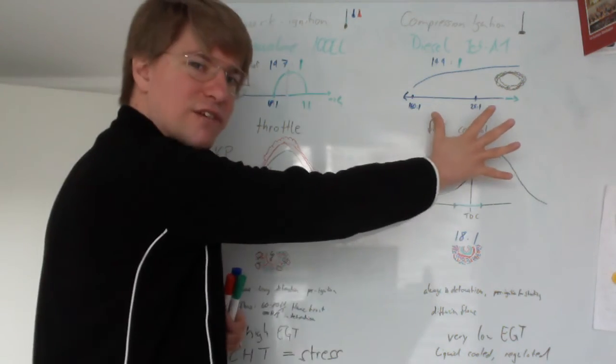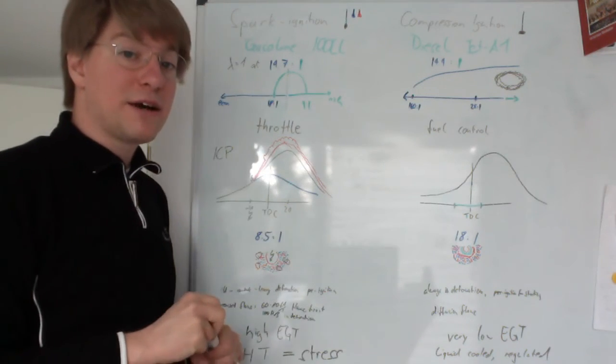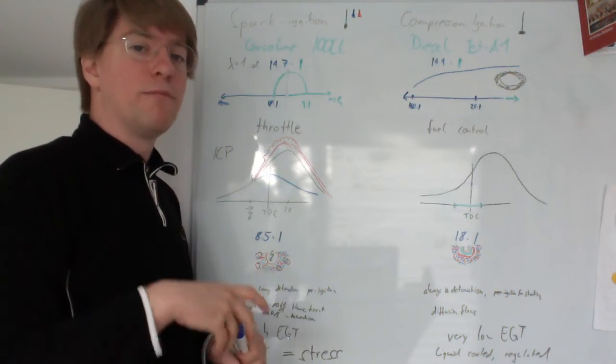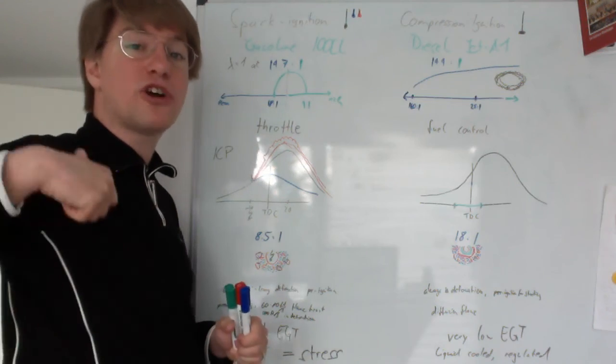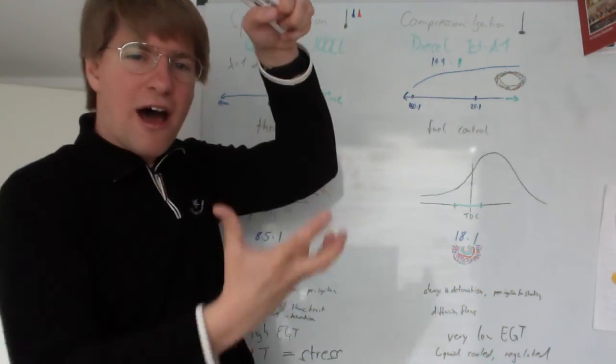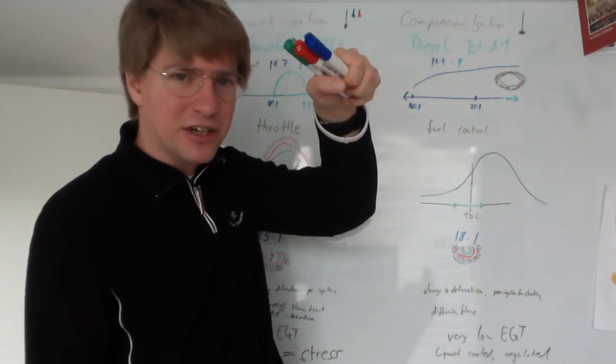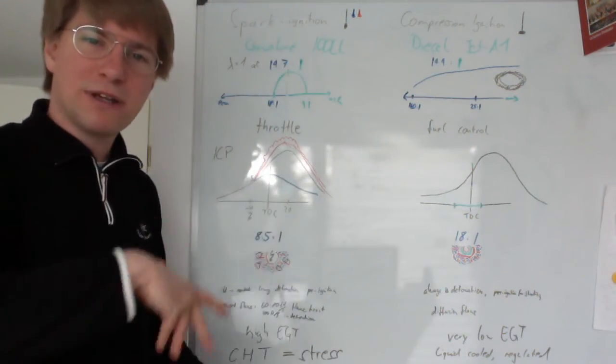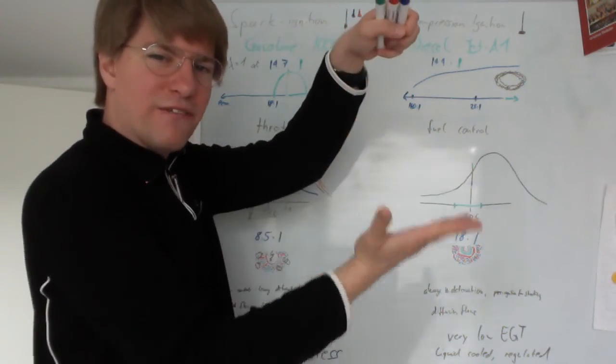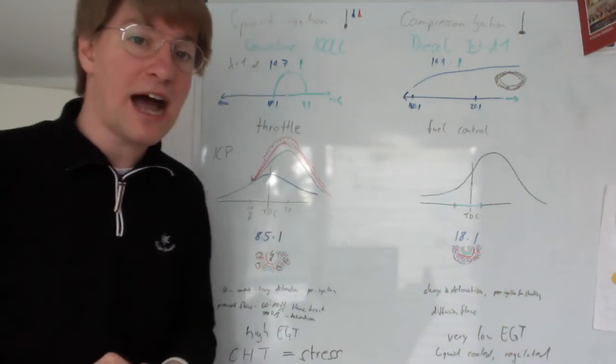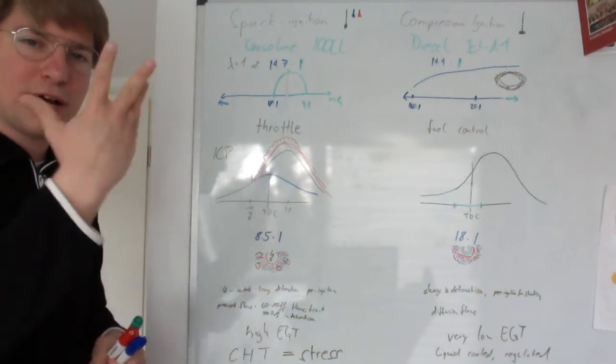The benefit of this is that the combustion is extremely efficient, due to the high compression ratio, which also means there is a lot of room for expansion when the combustion happens, because you're increasing the volume in the cylinder 18 times as the combustion is going.